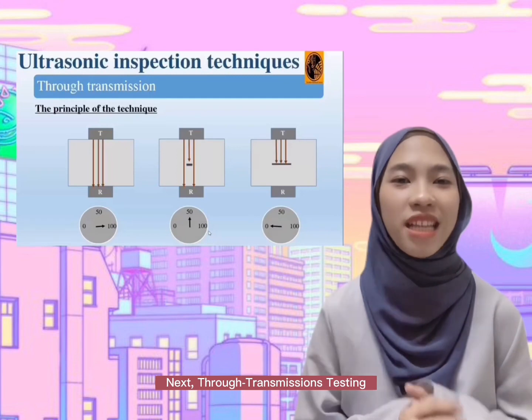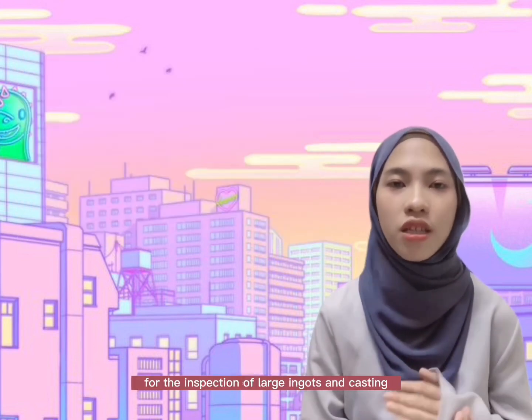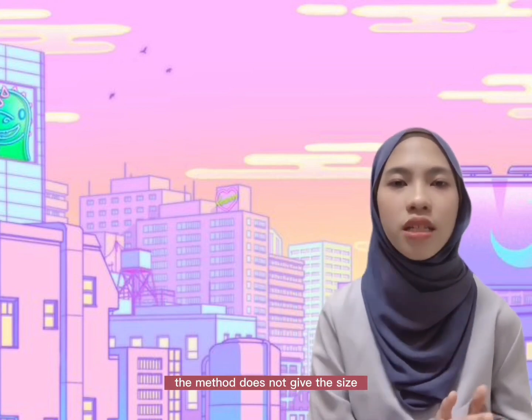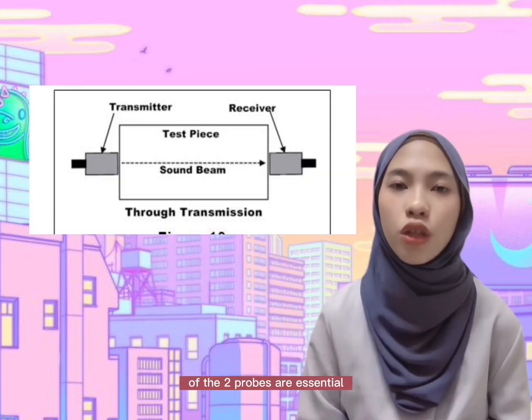Next, through transmission testing. This method is used for the inspection of large ingots and castings, particularly when the attenuation is high and gross defects are present. The method does not give the size and the location of the defects. In addition, good mechanical coupling and alignment of the two probes are essential.